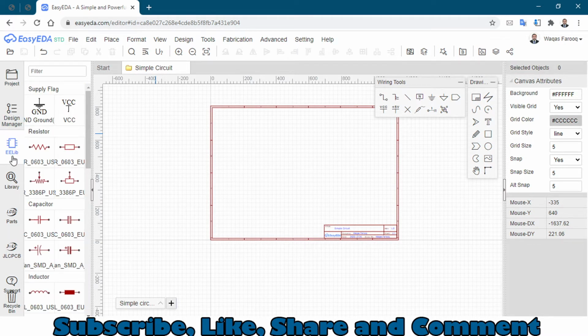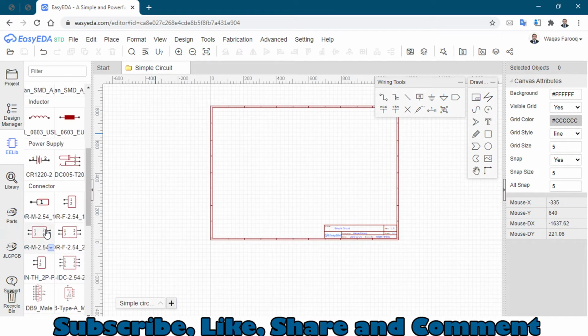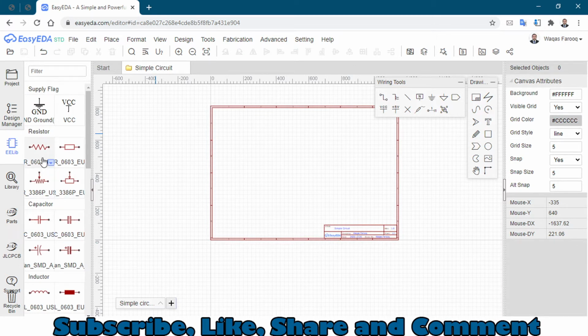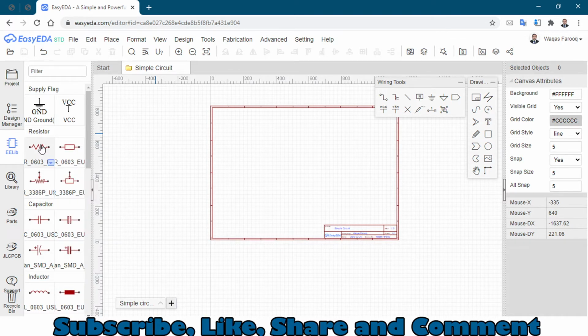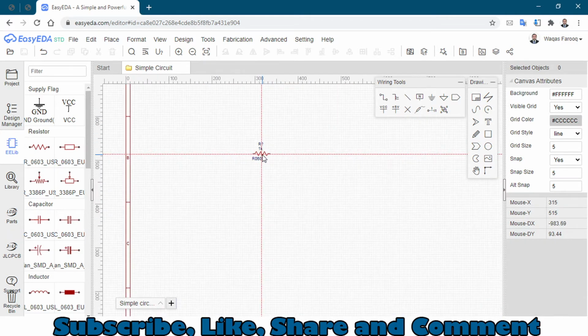Now you have to go to the EE library, where you can get all the components that you want. So let's just say we will get a resistor. There are different types of resistor: axial resistor or SMD. These are the SMD resistors, and these are the axial, which are THT resistors. If you don't know the SMD and THT resistors, you can search it online. So I will be using this resistor, and click on it and place it on the sheet right here.